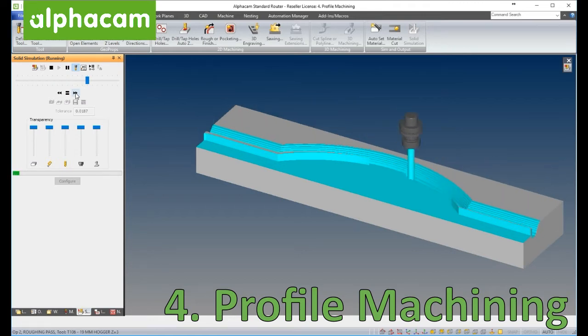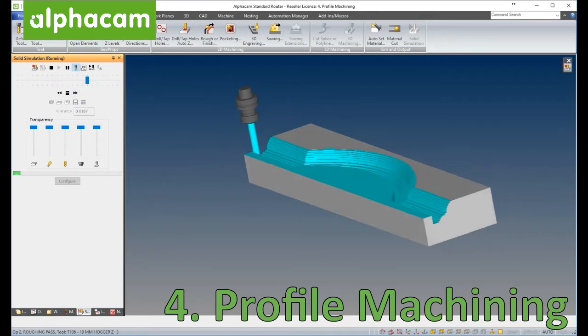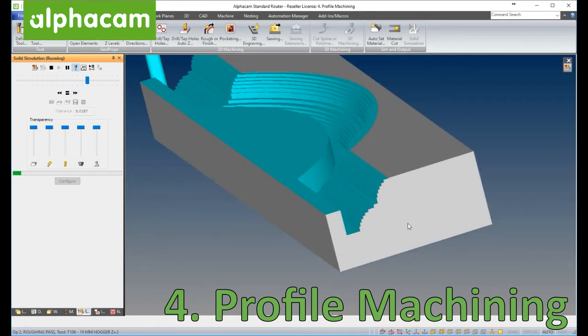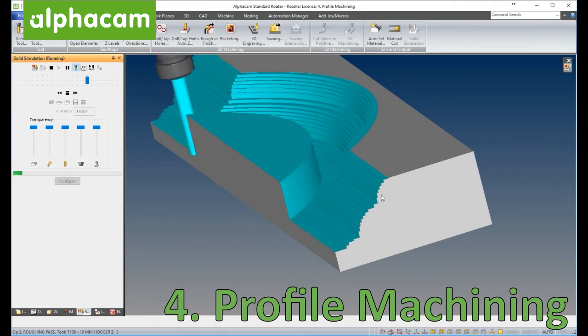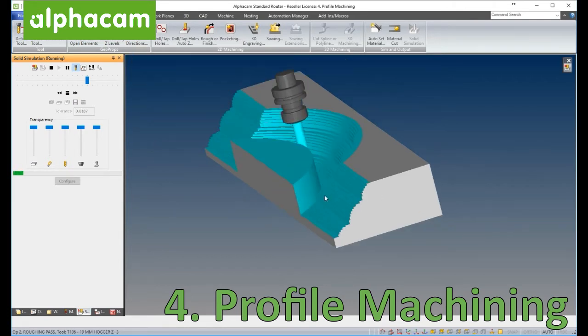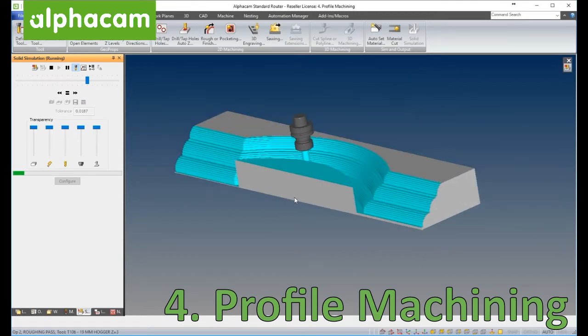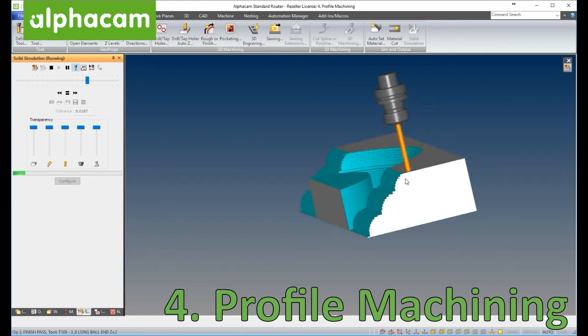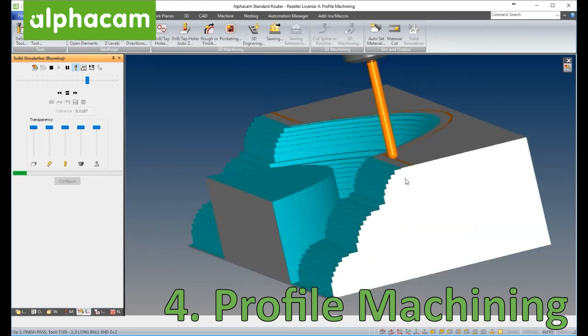This secondary operation is a roughing operation where I am now beginning to bring down that profile into steps that are, I think, about 6 millimeters or 1/4 of an inch deep. At that moment in time, we switch to a 1/2 inch or 3/8 of an inch ball end mill.